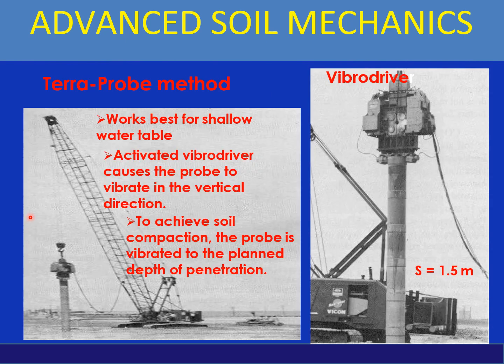So here you can see the terraprobe method works best for shallow water table. Activated vibro driver causes the probe to vibrate in the vertical direction. To achieve soil compaction, the probe is vibrated to the planned depth of penetration. So this is vibro drive.